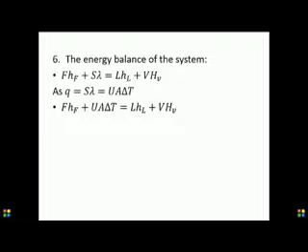As the heat transfer in the evaporator Q equals Sλ, which is also the same as UAΔT, the equation will become FHF plus UAΔT equals LHL plus VHV.